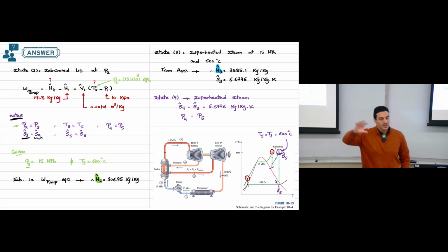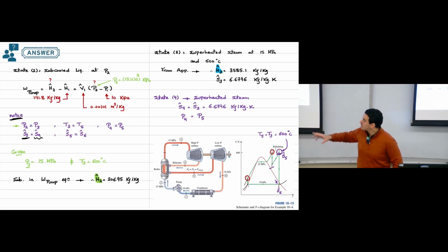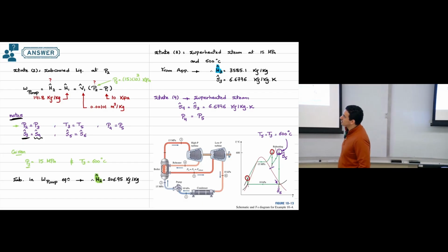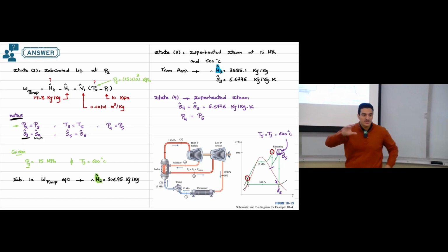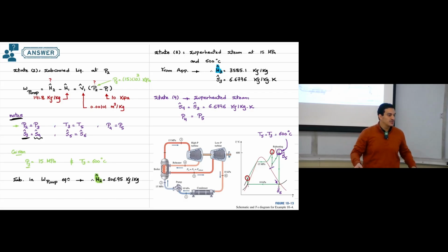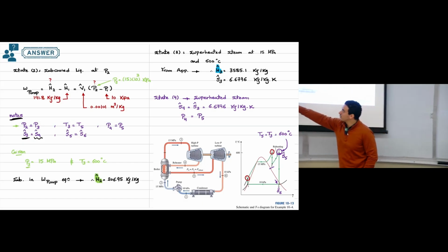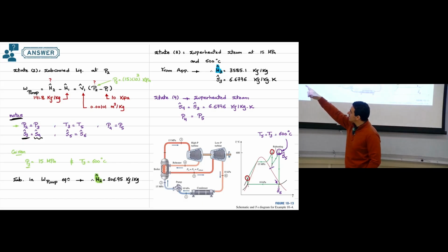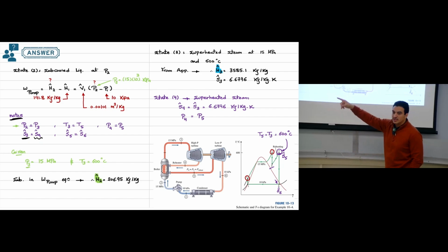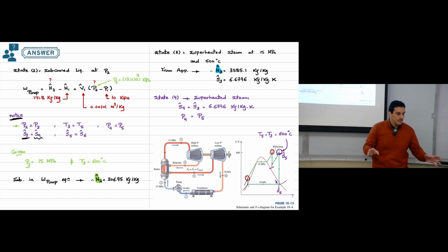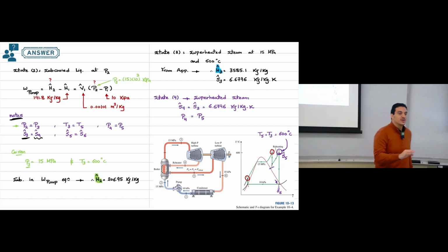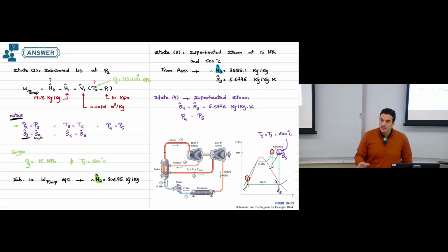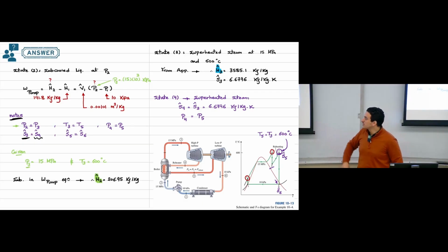Entropy at one point can be the same as another point. All of these observations or notes are based on understanding of the changes or the processes we have in the cycle. Okay? So without these things, we cannot proceed, because as you can see, we use entropy at point number 4 to find data at 3, because they have the same entropy. Entropy 5, entropy 6, they have the same entropy. Okay, so it is very important to keep these notes in your mind.